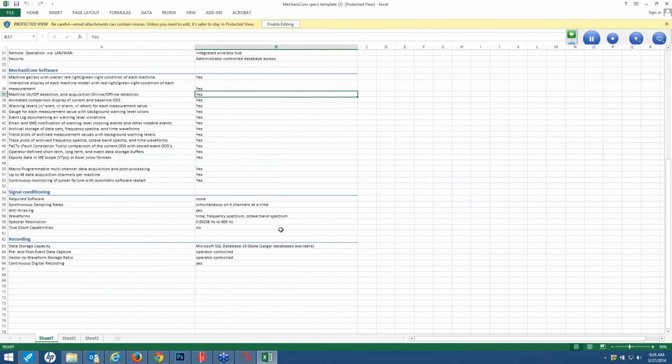The batteries are essentially wheelchair batteries, but the capacity on them is really good. You can do, I think, about 3 minutes worth of acquisition every day, and when the computer shuts down, when that's not running, it'll run for up to 9 months. So a lot of people go out there and maybe take one acquisition every 3 hours or something like that on a bridge and just have it wake up and then shut back down, and they can leave it out there for a month, no problem, and acquire that data and then bring it back and look at it. Okay. Or you can look at it real time in that situation. You can have a cellular card broadcasting the entire time. You can access it via the internet that way too.